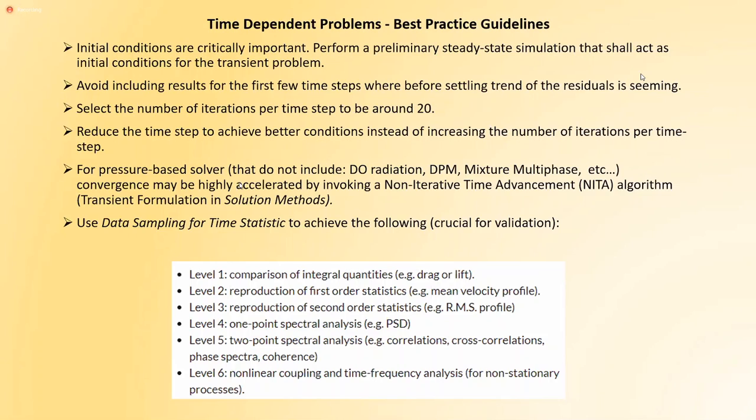For pressure-based solvers, it does not include the radiation and so on. Convergence might be helped by the algorithm that skips some of the steps. When some parts of the pressure-based solver converge, it doesn't touch them anymore. You can use that.